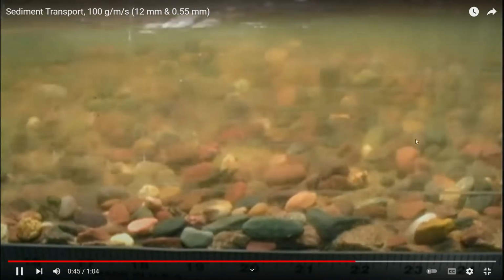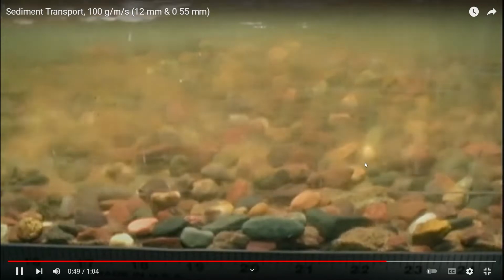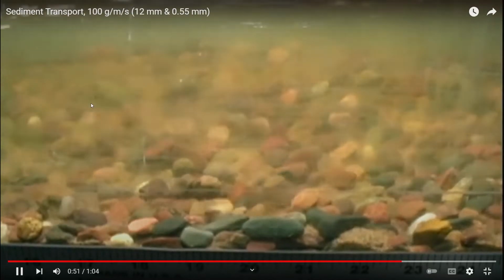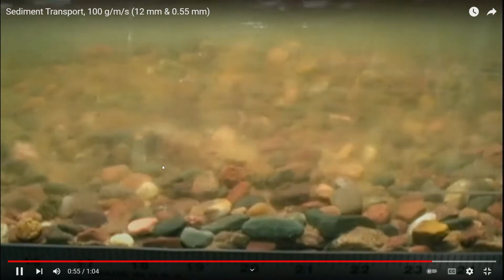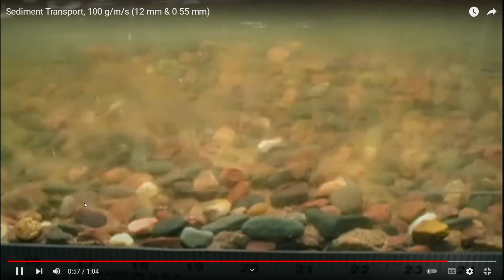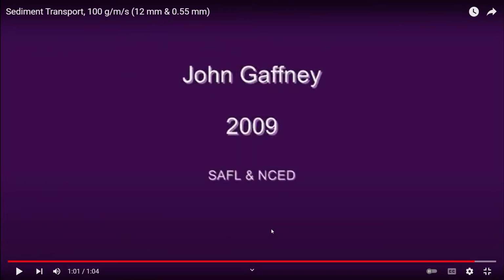And all of the transport that we're seeing is right along the bed of the river. And so this is a good example of bed load transport. Everything's being transported along the bed of the river. Okay, either saltating or kind of rolling or sliding. Even the little bits of sand are kind of making short hops rather than going up into the flow and actually getting transported a long, long way downstream.